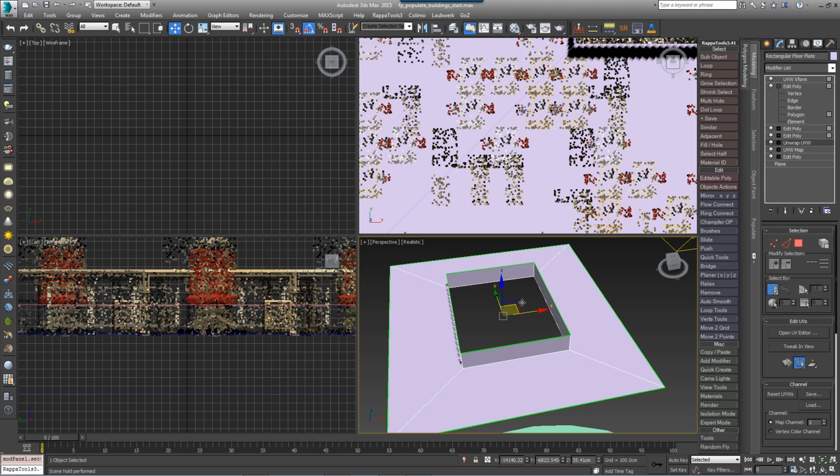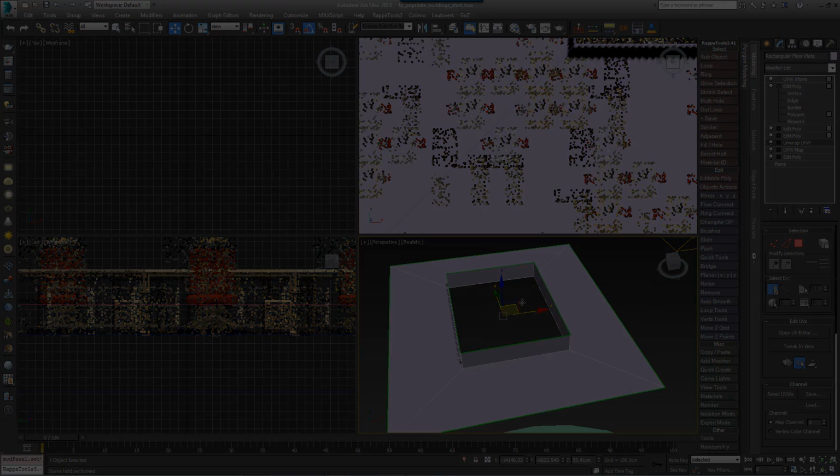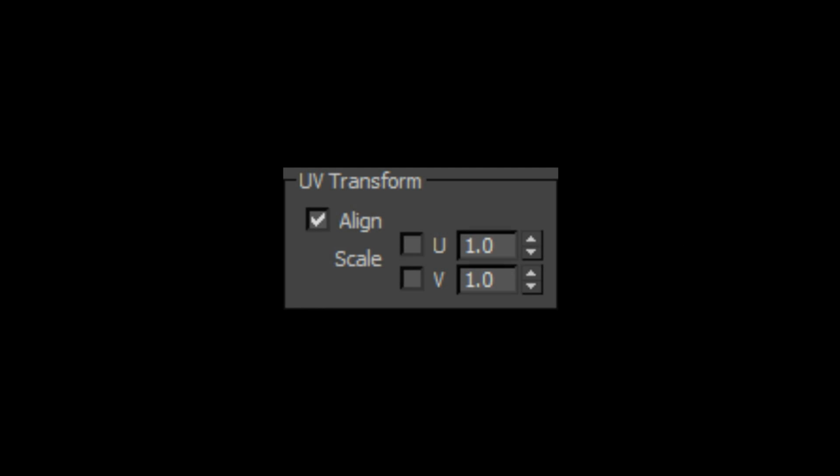Ideally, we'd like the desks to rotate to remain in the same alignment in relation to the building's footprint. We can't use the transform by map settings for this because the desks, chairs and computers are grouped, so they'll only rotate around their own local axis. Luckily though, we can achieve this effect by aligning the scattered objects using the surface's UVs.